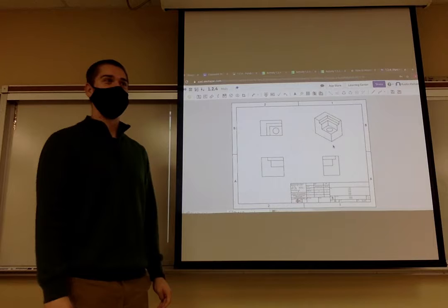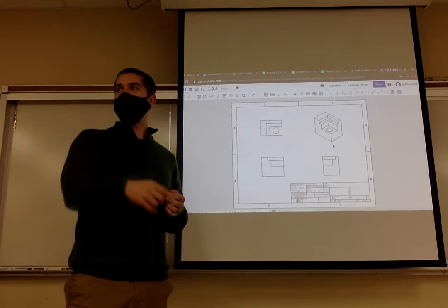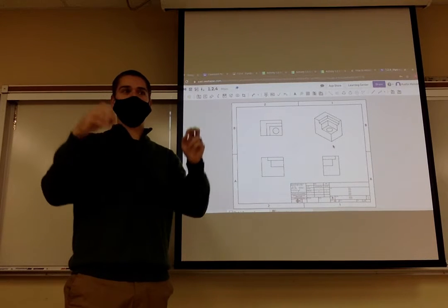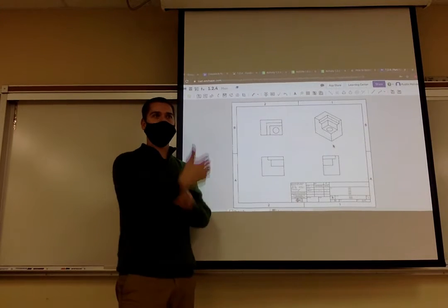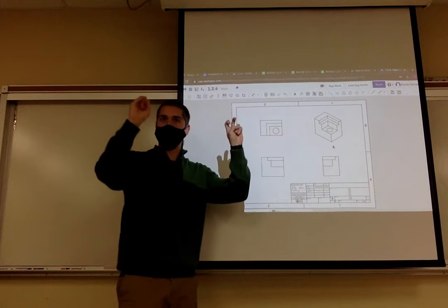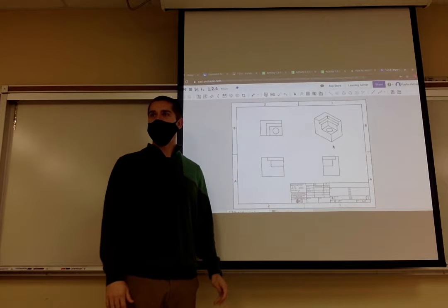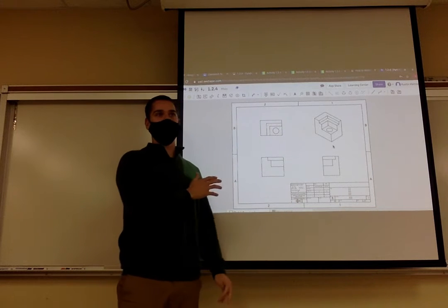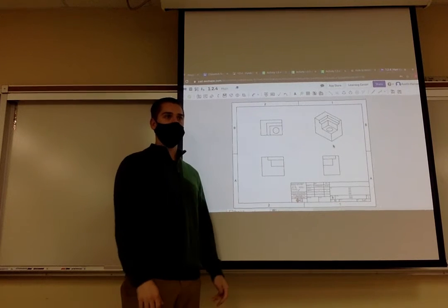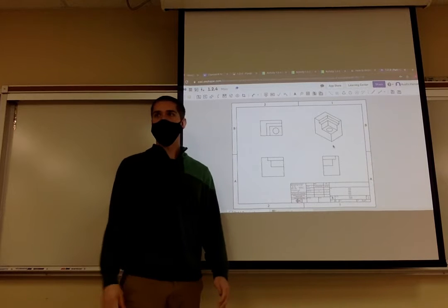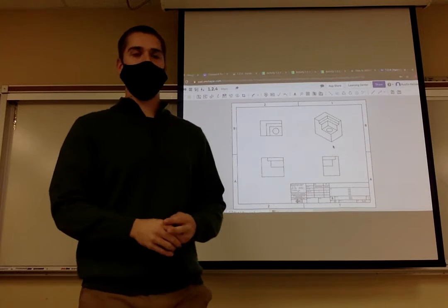Right? So I needed you guys to show me you could do this on your own, because sometimes you don't want these views. Or sometimes you've made your shape where Onshape thinks this is front, the way you designed it, but you designed it facing the other direction. So it'll do the front view, but the way you drew it, it's actually the back side of the object. Our front view is the best perspective, not the front in Onshape, because I could have made this part rotated. Well, then Onshape thinks of everything backwards. So sometimes you might do this and you might have to fix it. So at least I want you to know how to make a part drawing manually.